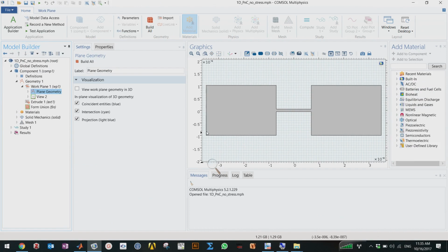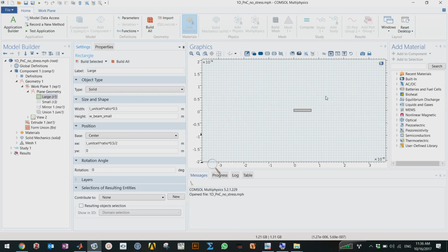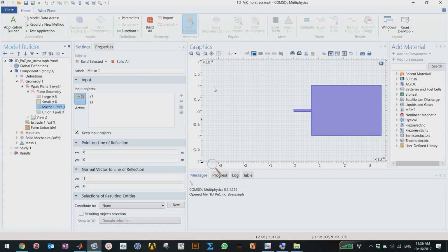The next step is, if you run it now, COMSOL will ask you what the material is. This is the material that I use: silicon nitride. Let me magnify it a bit. Here I use silicon nitride for the whole structure, and for example, you can see material properties like the density, Young's modulus, or Poisson ratio.